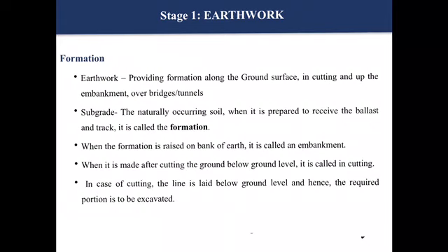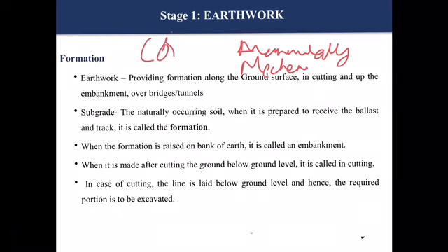In light earthwork, the excavations will be carried out manually, whereas if heavy earthwork is involved, we will go for the use of machineries to do the earthwork. And now, what is the cost of earthwork? That depends upon three main parameters. The first one is the type of soil. The second one is the hauling distance, and the third parameter is lift.